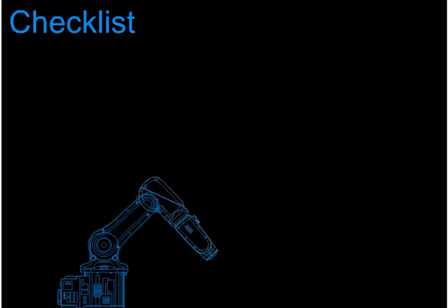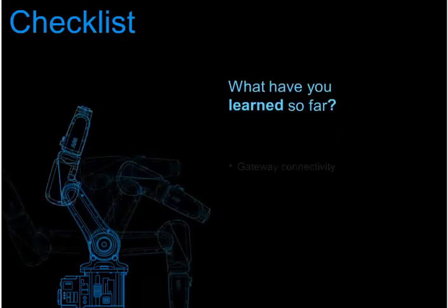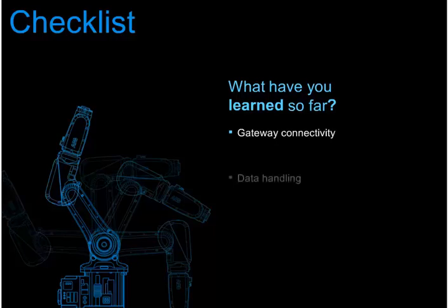What have you learned so far? A WirelessHART gateway needs Ethernet and a 24-volt power supply to operate. Data is cached and provided via HART, Modbus, or OPC. Locating the gateway must be well considered, depending on the need for less cabling or highest flexibility. Up to 250 devices can join one gateway. The actual amount depends on the update rates.